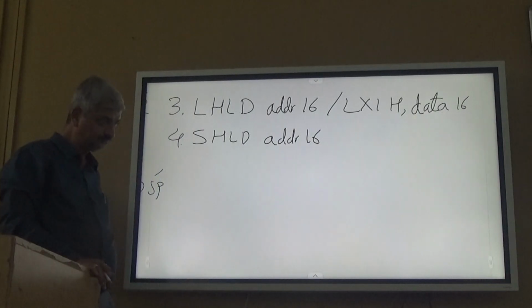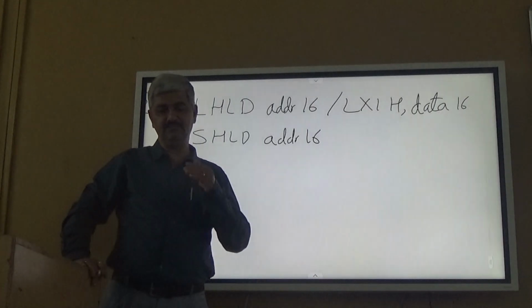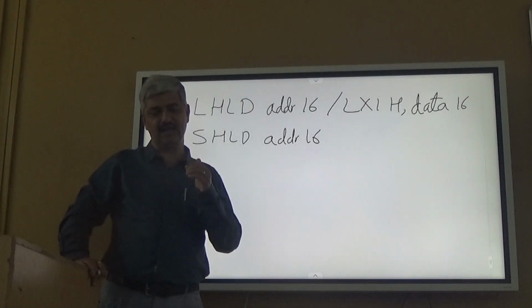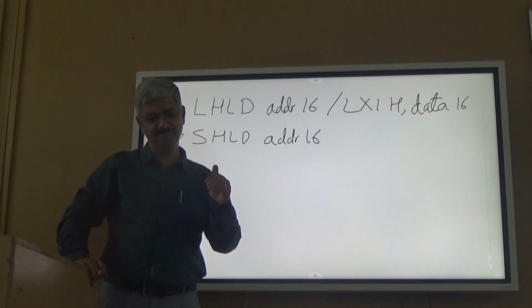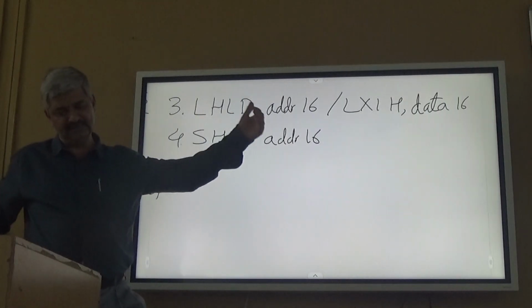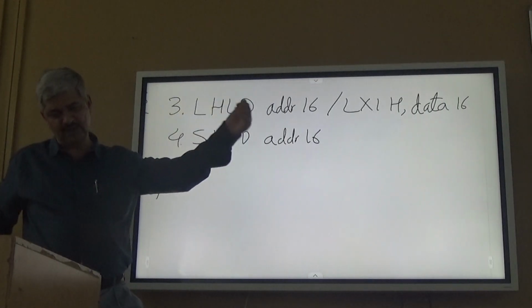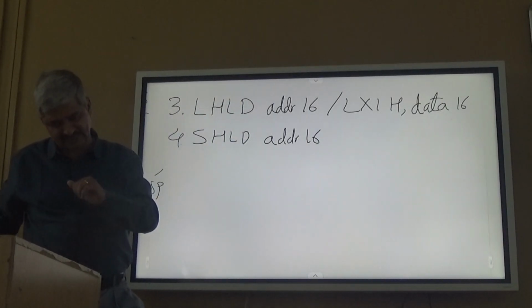Now there are 2 more instructions provided. When I want to bring data from external memory inside the processor, I can bring it in many ways. LDA I can bring, MOV A comma M I can bring, 16-bit LHLD I can bring.